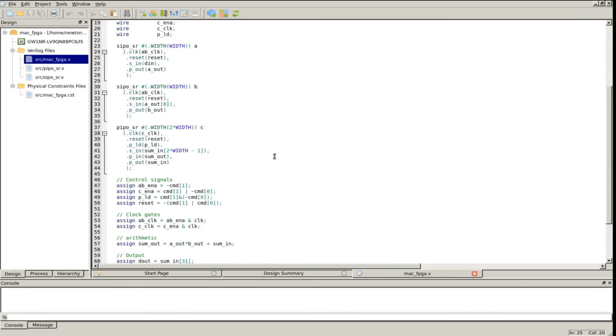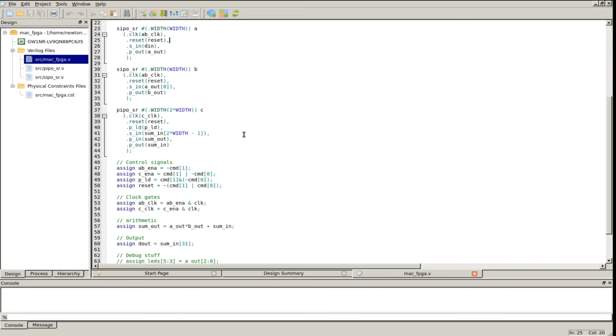And let's see, we have to look at how the control signals are formed. That's combinational logic. These assign statements essentially create combinational logic blocks that do the right thing. The operators are expressed in the select notation, for example. That's a bitwise OR, a bitwise AND, and a bitwise NOT. So it's very easy to form those control signals.